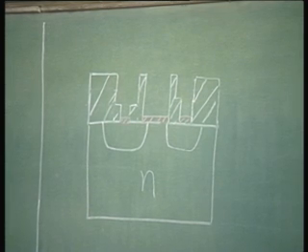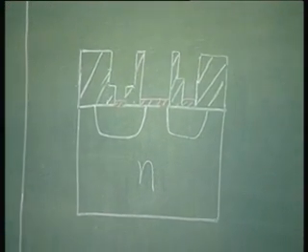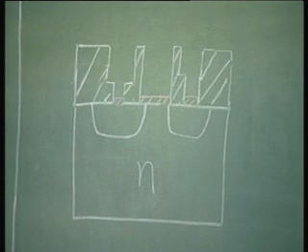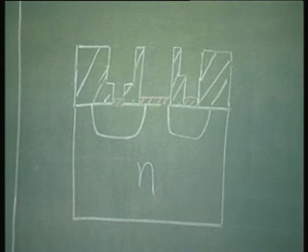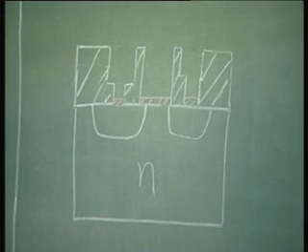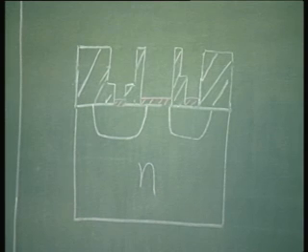That is, we have opened windows in the gate region and also over the source and drain, and then subjected it to a process of very stringent quality oxidation and grown a thin layer of oxide over this gate region and also over the source and drain. Okay?